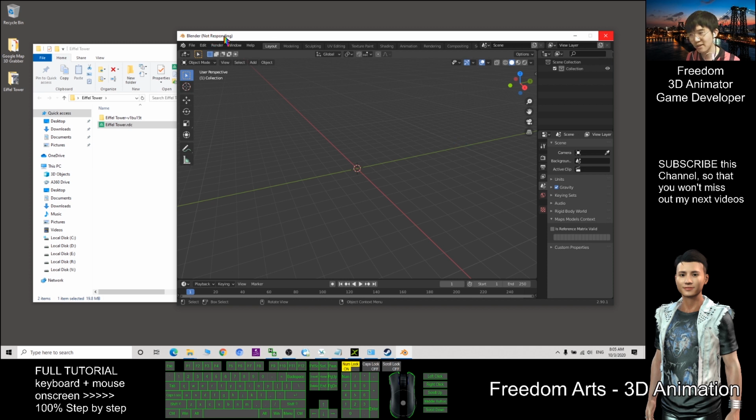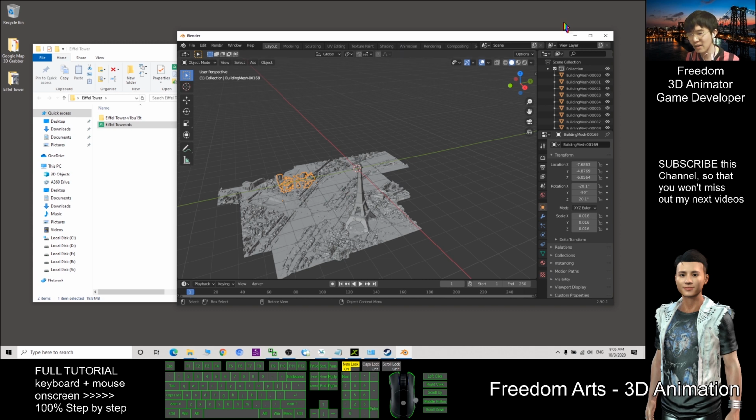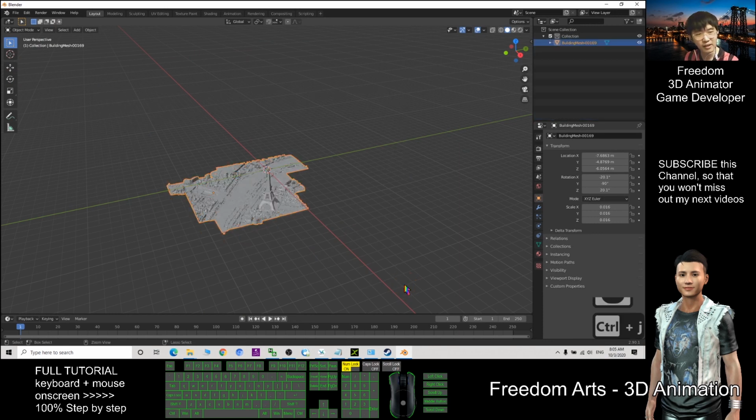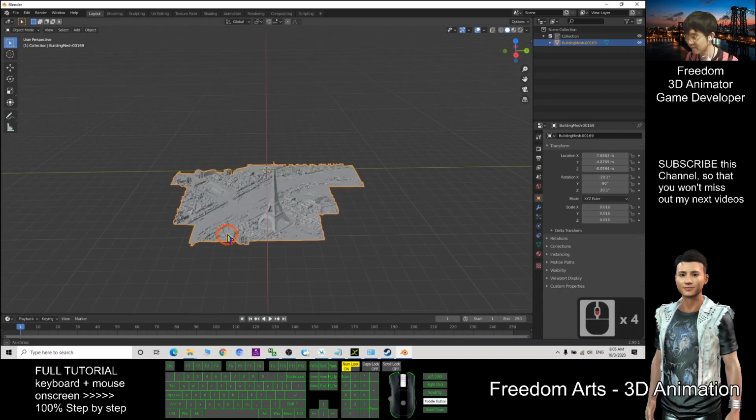Wait for a while. It is not responding, but you do not close it. It is loading the 3D models. You need to wait for a while, and now it all comes out already. Now, the first step you need to do is select all in this way. Press Ctrl J to combine all the mesh to become one.